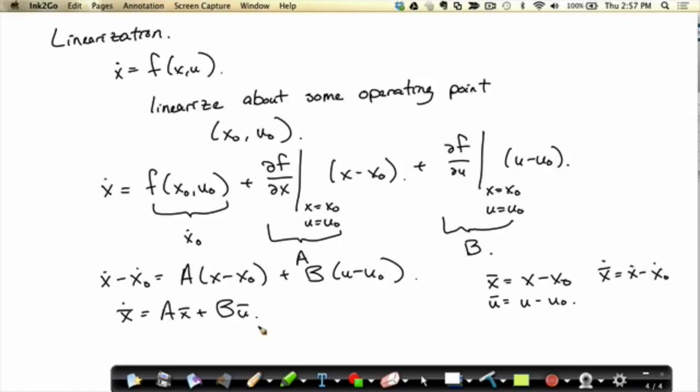Okay, so that's probably familiar, but the mechanics are very simple for taking some function f, even if it's got the inverse mass matrix, even if it's got all these things in there. It's just a matter of taking a few gradients and you can come up with a linear approximation of the system. And the big question I want to ask is: is that a faithful representation of the nonlinear system? Of course, it's not going to be a perfect representation. To what extent is that a faithful representation of the nonlinear system? And what utility is it going to have in nonlinear control design, right?